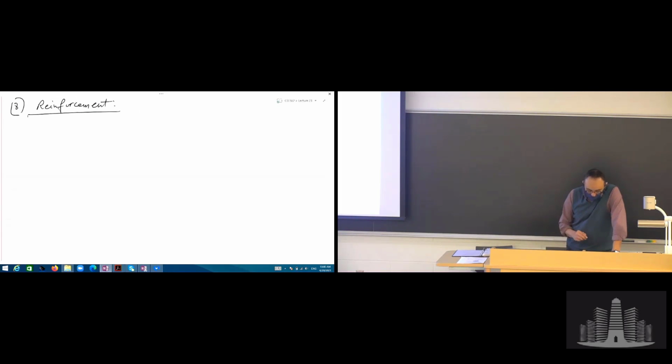All right. The reinforcement is in the form of steel plates. The minimum thickness as per AASHTO for the steel plate that you should use in these types of bearings is 0.0625 inches. So that's one important piece of information. Now, as we said, we are going to check this under service limit state.